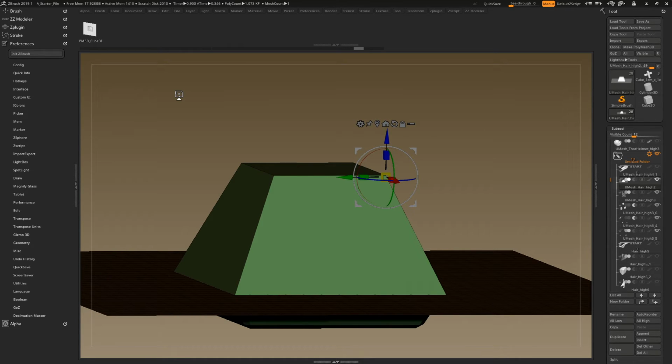So if you make a mold out of, say, for instance, latex, it over time breaks down and it reduces in size. That's shrinkage. It's a very different thing. Overbake and light bleed are the two biggest problems of SLA. Light bleed is usually when your housing isn't fully enclosed properly, and light is spilling into the baking area, and that'll mess you up.